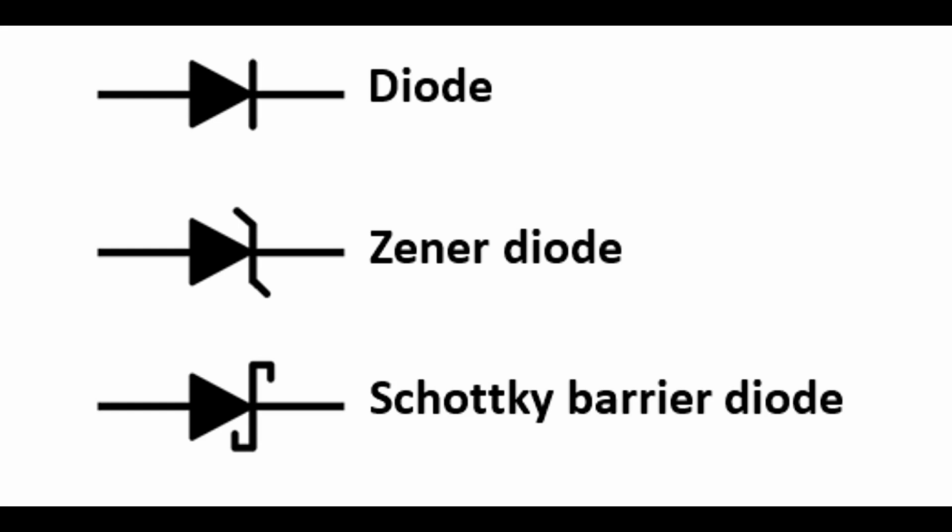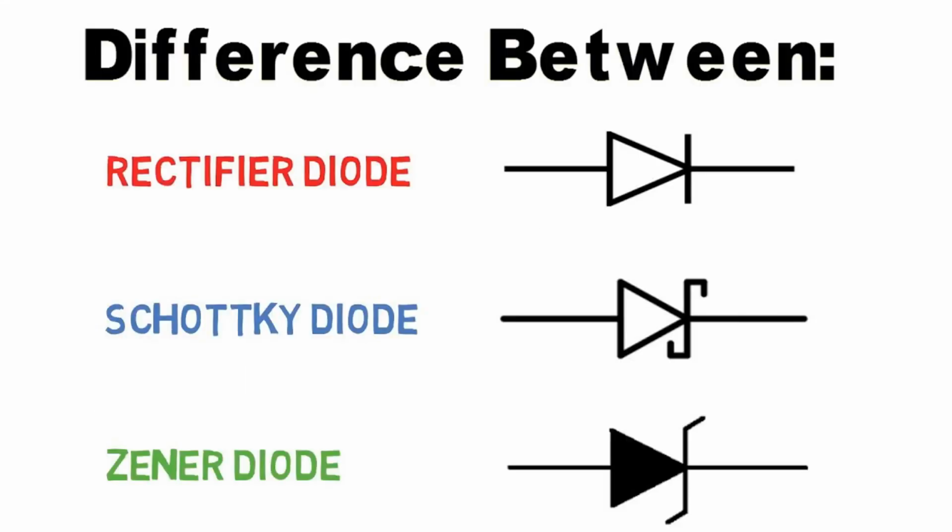2. P-N junction. Most solar cells have a P-N junction, which is a region where the P-type semiconductor, with positive charge carriers, and the N-type semiconductor, with negative charge carriers, meet. This junction plays a crucial role in the separation and flow of charge carriers during the photovoltaic process. 3. Solar cell efficiency. The efficiency of a solar cell refers to the percentage of sunlight energy that the cell can convert into electrical energy. Efficiency varies depending on the type and quality of the semiconductor material, with commercially available solar cells having efficiencies ranging from around 15% to over 20%.